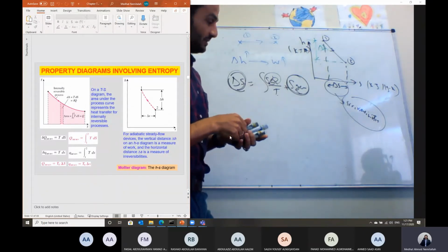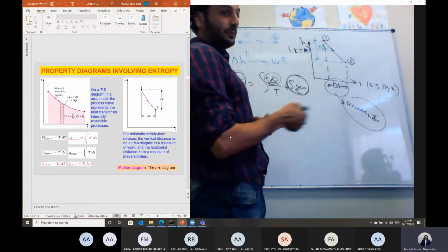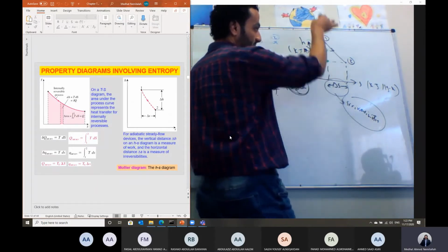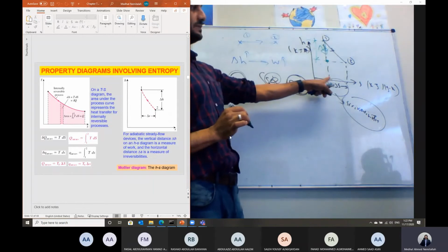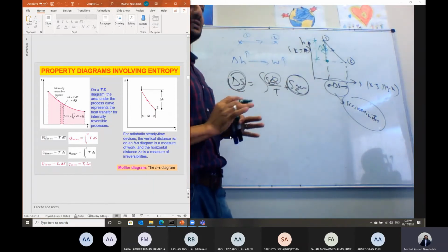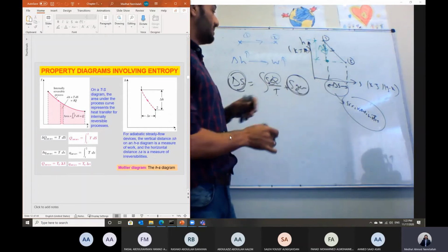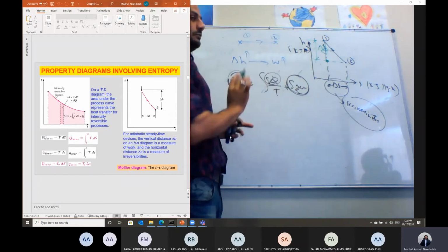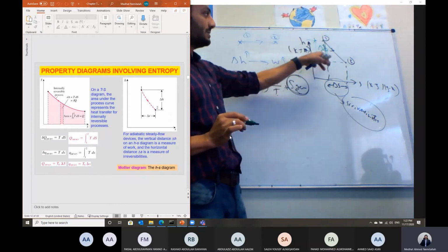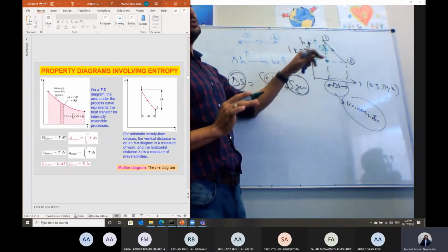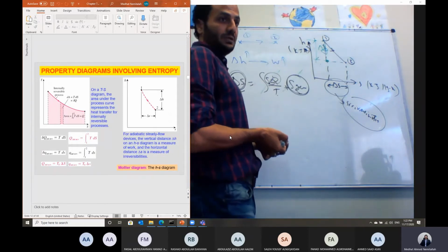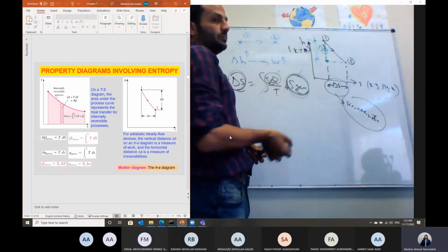And that's why, Shabab, if we have an isentropic process, isentropic means what? The process is just vertical. Delta S is equal to 0. An isentropic process means the process is reversible. In this case, delta S is 0. That means we don't have any kind of losses within the system. So the losses are 0 if the process is isentropic. But usually for any actual process, we should have some losses, and in this case, some entropy should be generated.